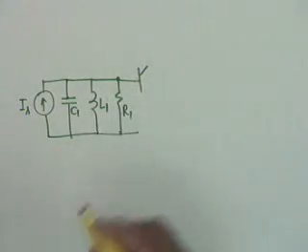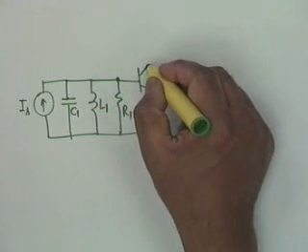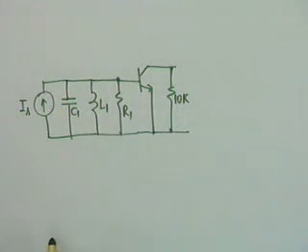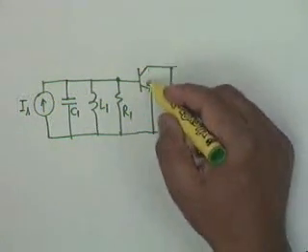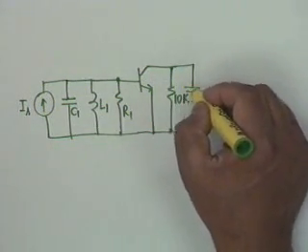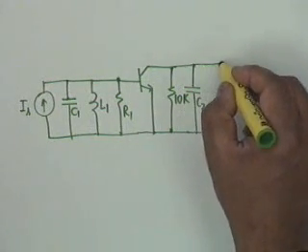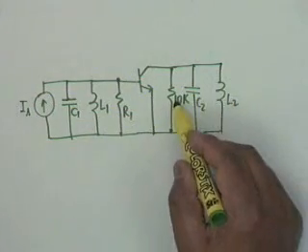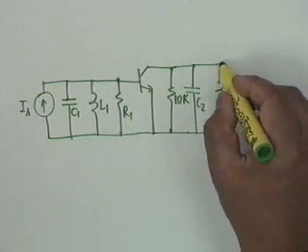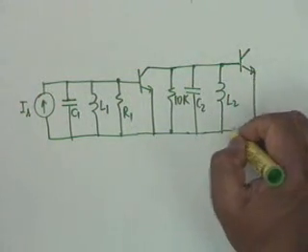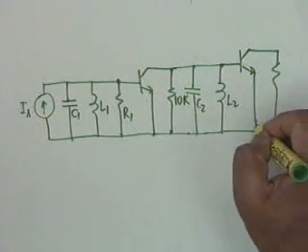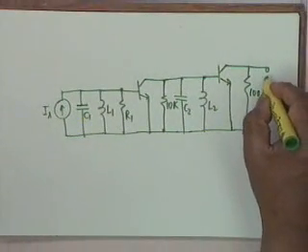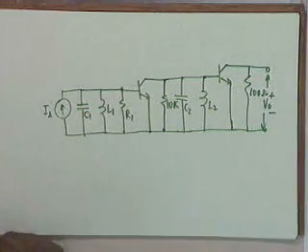Then you have, this is one of the tuned circuits. The other tuned circuit comes in the load or in the collector circuit of this transistor, and for biasing and other considerations, this resistance is 10K. Then you have a capacitance C2 and inductance L2. Once again, we assume that the parallel resistance of L2 has been absorbed in 10K. All right. And then you have a second transistor whose load is 100 ohm, and this is the output. For variety of experience, we assume that the output is the voltage.